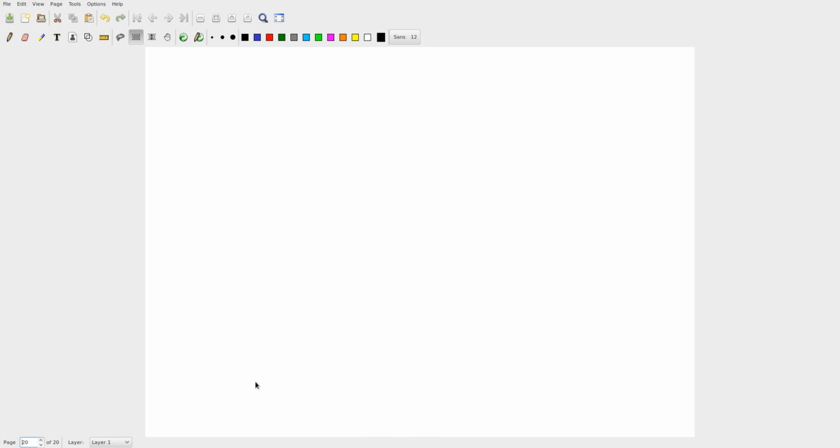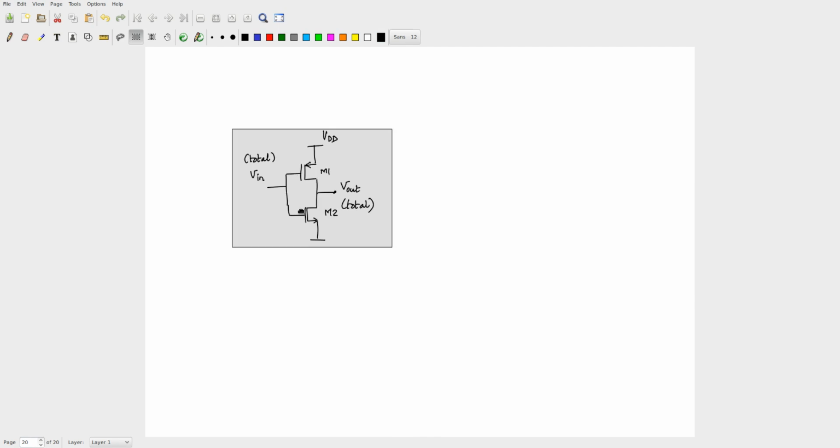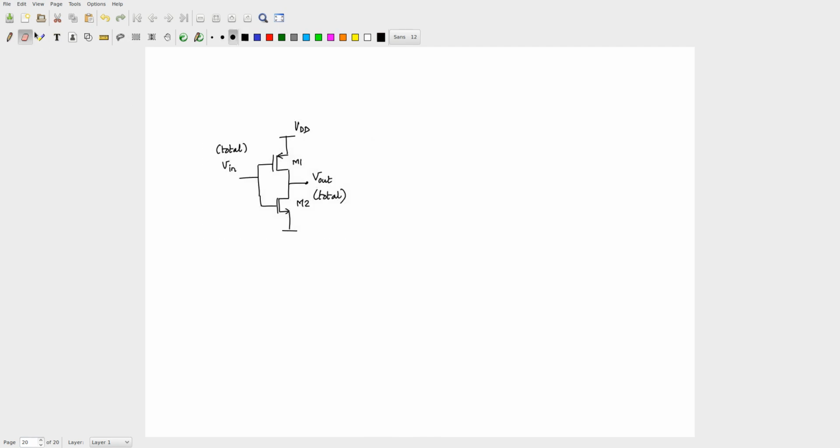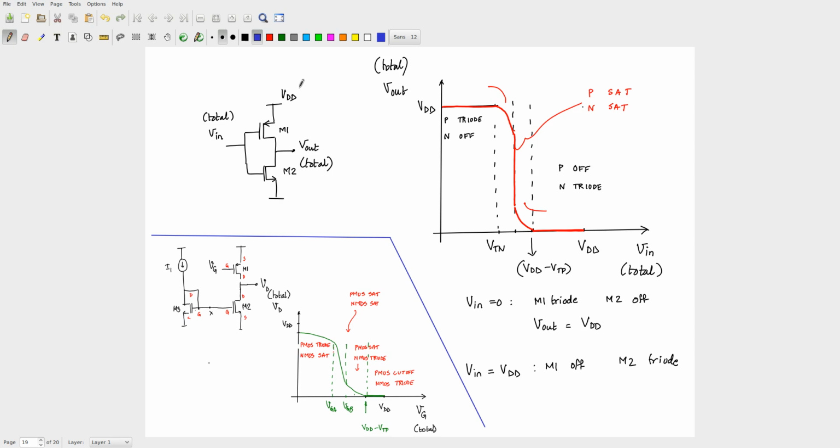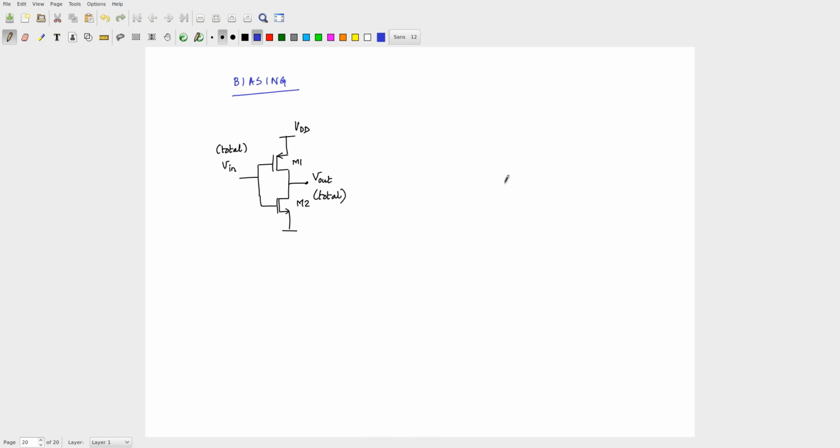That bit is to do with how do you bias this transistor. Okay, so biasing of this circuit is very difficult, because your bias should be such that both are here. That's a very, very, very narrow window. If you are out of that window, you won't get any gain. Correct? But at least we'll see in the lab how you will effectively do it in practice. But one can try and estimate that. So, let me call that Vg. Now, it is without any capital, without any small letter for the V, because this is the bias voltage.